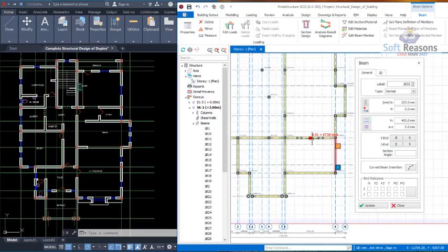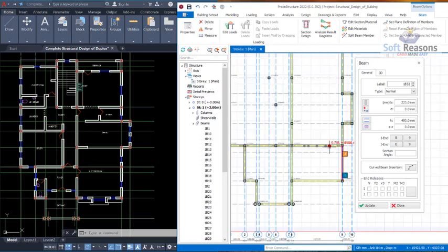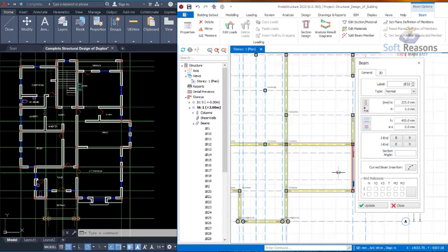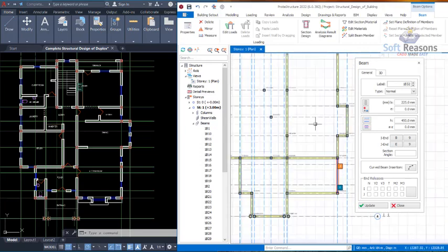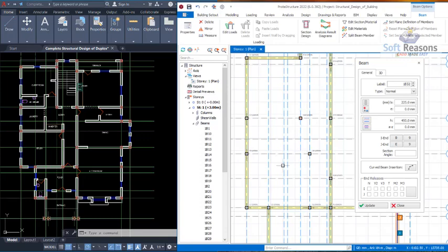Okay, we are not supposed to have a beam here as well, so we'll get rid of this beam. Because this is a city room, there should be no beams right there. If there should be a beam, maybe due to the area to be covered by the reinforced concrete slab, we should have a concealed beam and not a normal beam. So we look at that shortly.